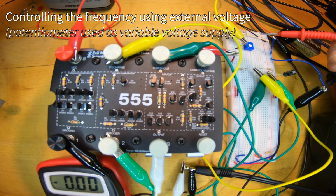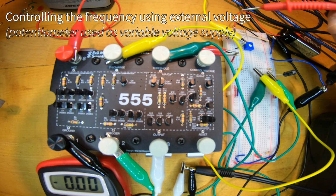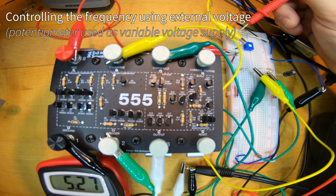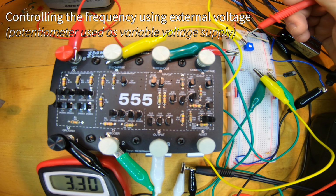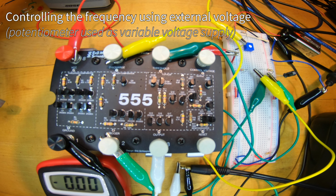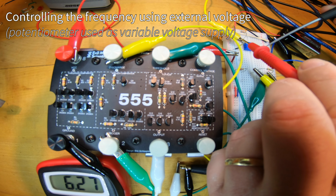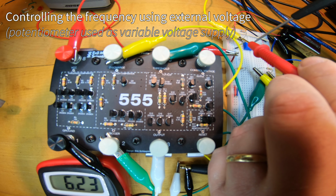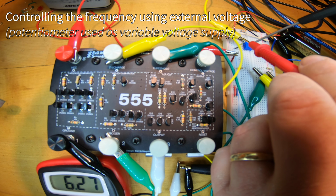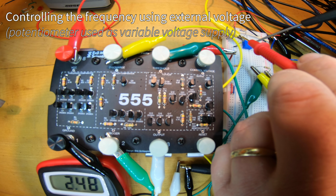I'm back to looking at the audio frequency, and I've created an external power supply, which for a moment is just a potentiometer, one leg connected to 9 volts, the other leg connected to ground, and you can see in the lower left-hand corner of the screen I've got the voltmeter reading. I've put a small resistor in series with the potentiometer so that I can never turn the pot all the way down to 0 resistance and have a short circuit. You can see on the output of the pot, the third pin, I am able to adjust the voltage down to 0 and all the way up to about 8.7 with the 9.3 volt battery.